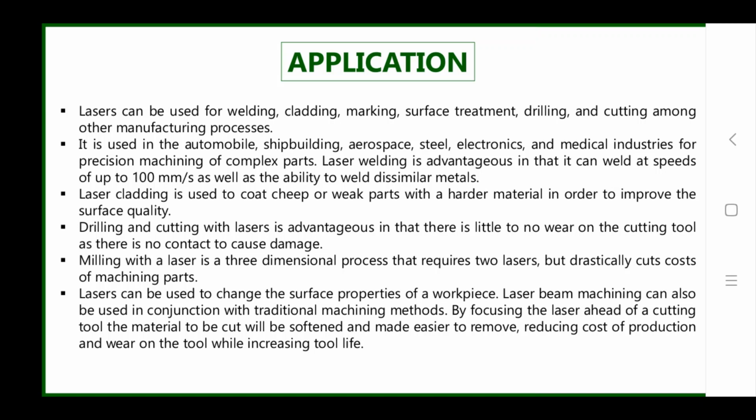Laser cladding is used to coat cheap or weak parts with a harder material in order to improve the surface quality. Drilling and cutting with a laser is advantageous in that there is little to no wear on the cutting tool, as there is no contact to cause damage.